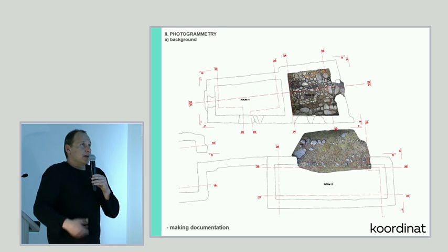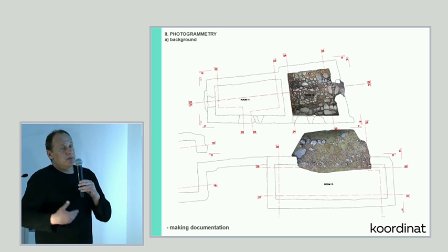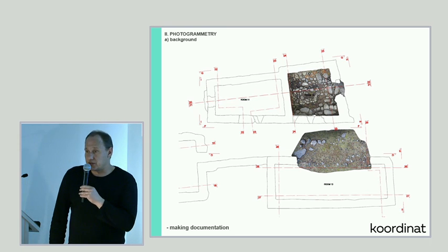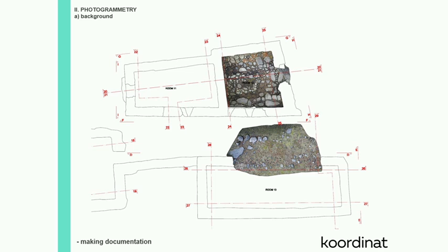What I was thinking about the better control is that when I am doing it surface by surface, I have ready surfaces to produce the 2D documentation. Of course, we all would like the three-dimensional models and environments to be used widely, but as of now, it's still the 2D that is most commonly used. So in that case, I can quickly produce ortho images. Ortho images have all the characteristics of a map, so you can make measurements upon them and extract the necessary vector data.